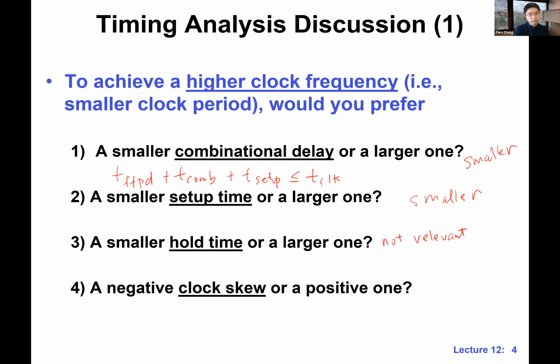Okay, this one maybe requires a little bit more thinking, and I need to remind you about clock skew. Negative or positive: negative means that the sending flop is seeing the clock late. Positive means the receiving flop is seeing the clock late. All right, very good. So we want positive. Positive is beneficial, negative is harmful.